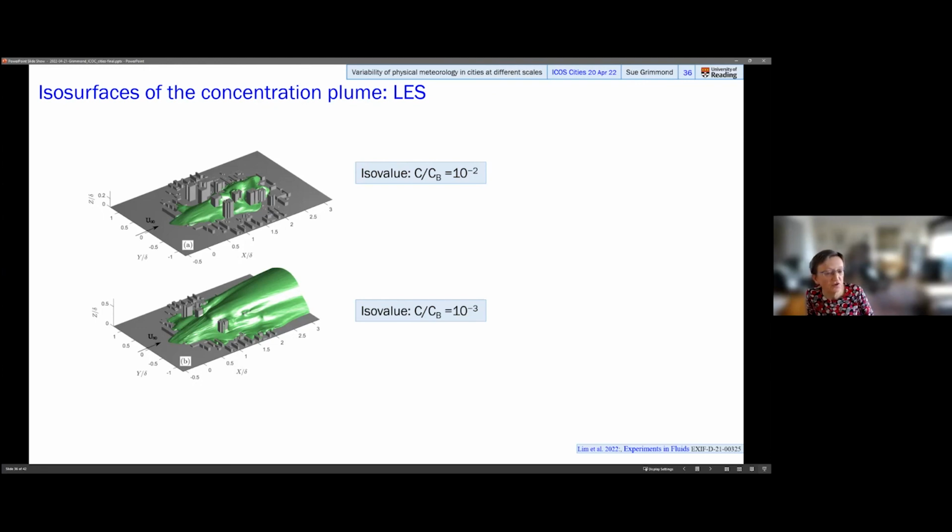because of the nature of the variability. There are observations done by difference, basically saying, can you measure all of the components and then assume that you've got the anthropogenic heat flux? With eddy covariance at the neighborhood scale, you can get the sensible and latent heat fluxes reasonably well if the sensors are well located, or with large aperture scintillometry.